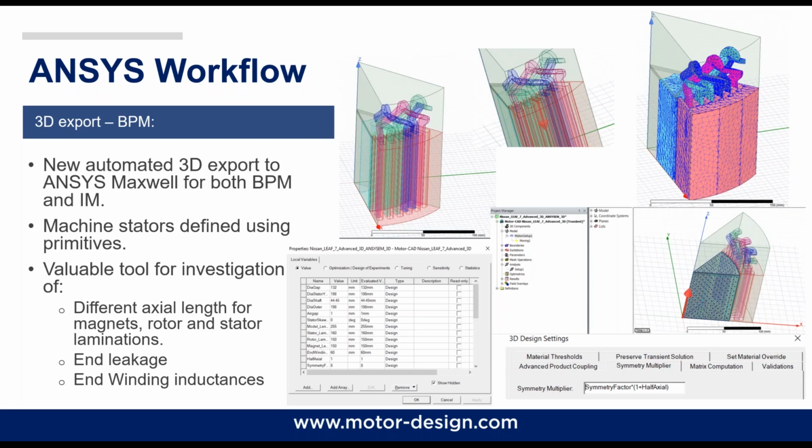And it's also worth saying that the same symmetry factor can be applied in the 2D model as well. Every model will always have 3 different bands in the air gap with 3 different diameters and axial lengths in order to have a good resolution for the mesh in the air gap. The bands need also to include all the rotating parts since they play an important role when the motion setup is given. Exported models will always be inside another band called region, which has to be filled with air, otherwise we couldn't get any acceptable results.